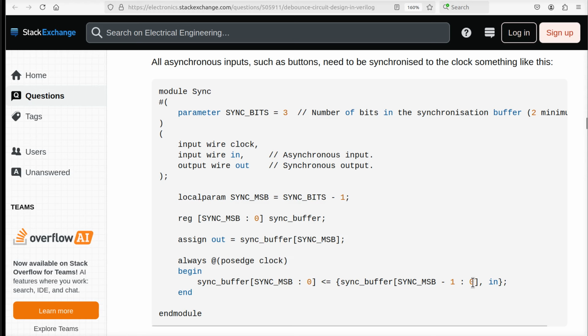You can see there's a shift register in here, and every time the clock ticks, he's got 3 bits here, and basically he's going to serially take the input bit. He's putting in the least significant bit and concatenating it with the prior 2 bits in a shift register, and every time the clock ticks, he just shifts it left.